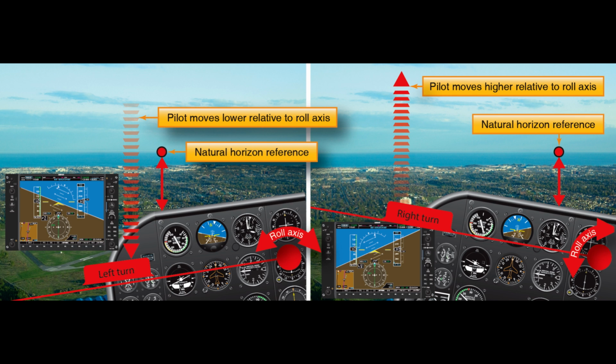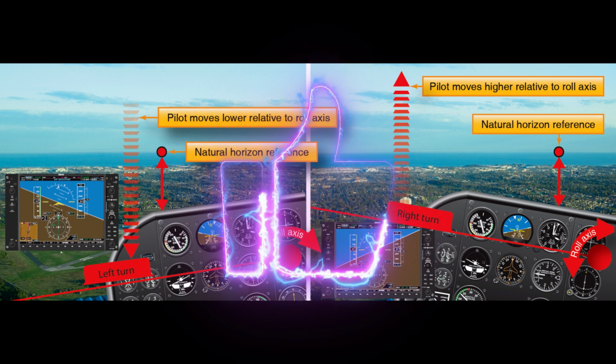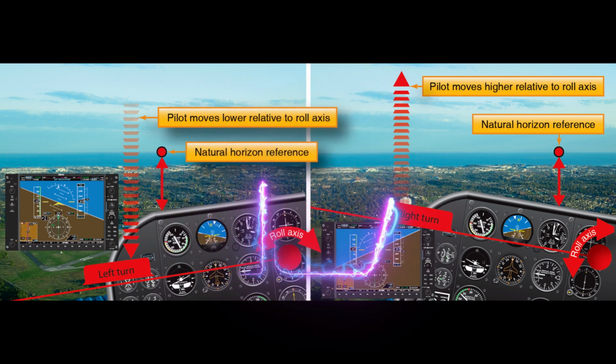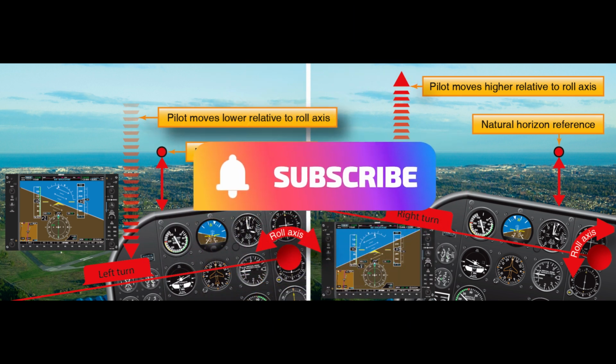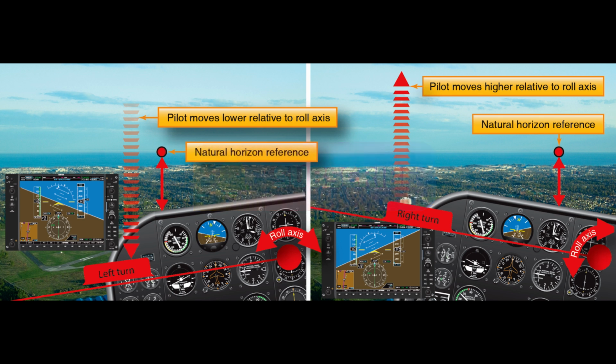applied. After the bank has been established, all flight control pressures applied to the ailerons and rudder may be relaxed or adjusted, depending on the established bank angle, to compensate for the airplane's inherent stability or overbanking tendencies. The airplane should remain at the desired bank angle with the proper application of aileron pressure. If the desired bank angle is shallow, the pilot needs to maintain a small amount of aileron pressure into the direction of bank including rudder to compensate for yaw effects.